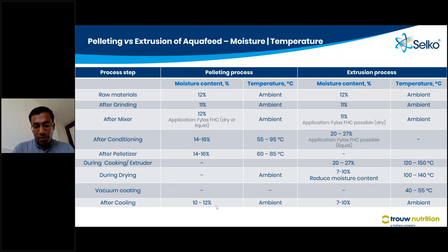All the production and quality people are looking to attain certain targets assigned depending on the product, and everyone is trying to stay below. But actually you have the possibility to increase the throughput, get the benefit out of it, and also avoid the risk of mold. In extrusion, you see you have a very high moisture. Of course, you're using much more than may be needed, because if you optimize, you may need less. If you use less here, you can dry less and get the right moisture in the end, reducing the energy needs for drying.